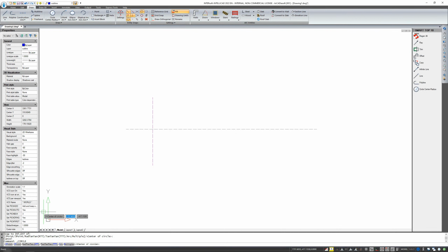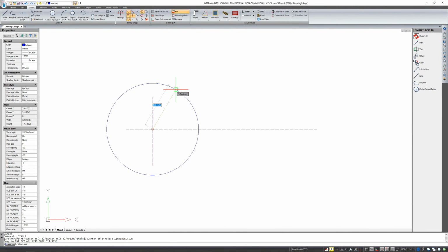Note that when you are in the command, so that you have the input window turned on next to the cursor, here at the bottom of the screen on the command bar, you also have information that you are in the process of drawing a circle. Then, if you choose anything from the set of snap points, the given point turns off all the other snap points. The ones that you have are fixed points. Now I only have the intersection point at my disposal. Please note these constant points are back on, and that one point has been turned off.